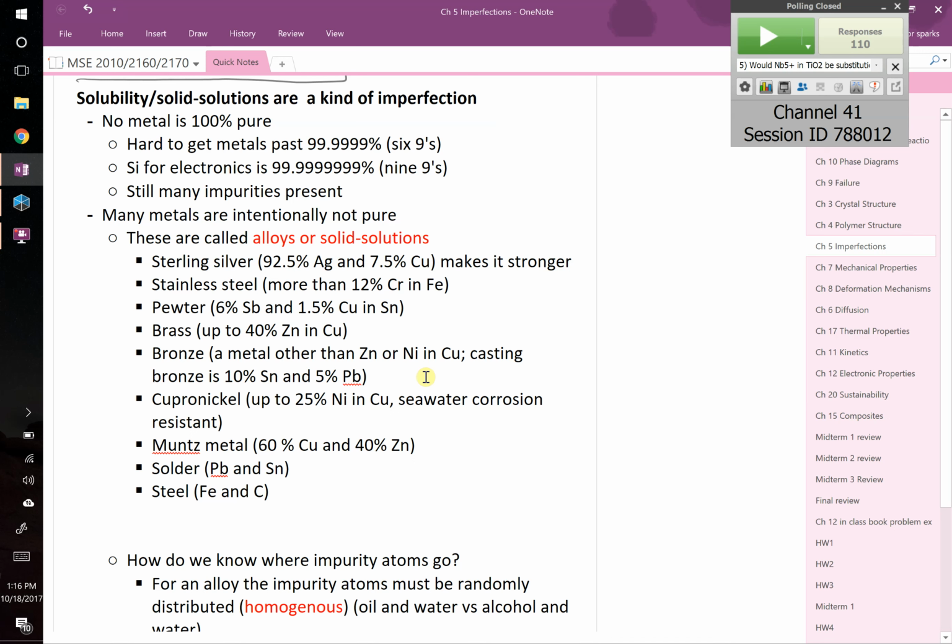When you buy copper from Kennecott or whoever your supplier is, they're going to give you some purity. And it's very hard to get past 6 nines. In fact, if you buy something with 5 nines purity, it already is starting to get very expensive. When I buy something, I almost never buy it that pure. We buy things usually 99.9 or 98.5% pure, depending on what the application is, because it gets really expensive, right? Typically because you have to separate these things with slow, tedious processes where you have slight differences in maybe solubility, so you might dissolve out some of your impurities, and you have to do this process over and over.